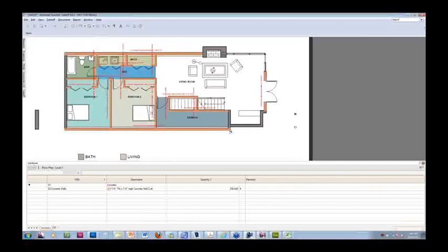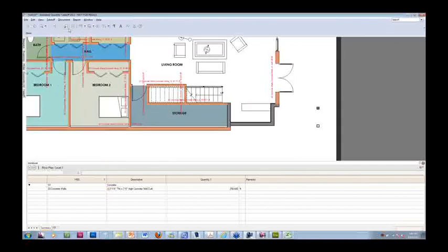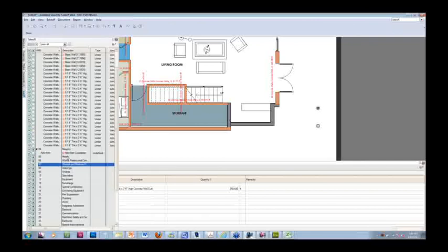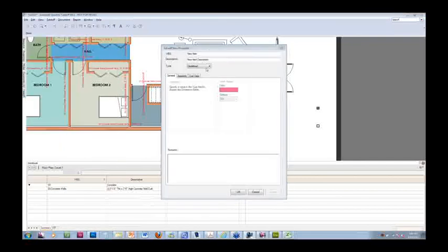So for instance, what if I had a wall here that is not even drawn? Well, I can easily just go to my takeoff, create a category, let's say for masonry here, and this is going to be maybe 12-inch masonry with something else, and then I can give it a description of the exact category, you know, CMU 3 by 3 by 3, whatever the type and category.